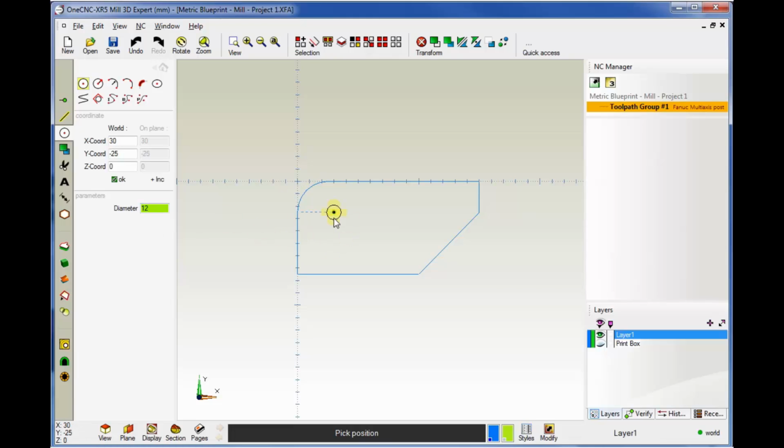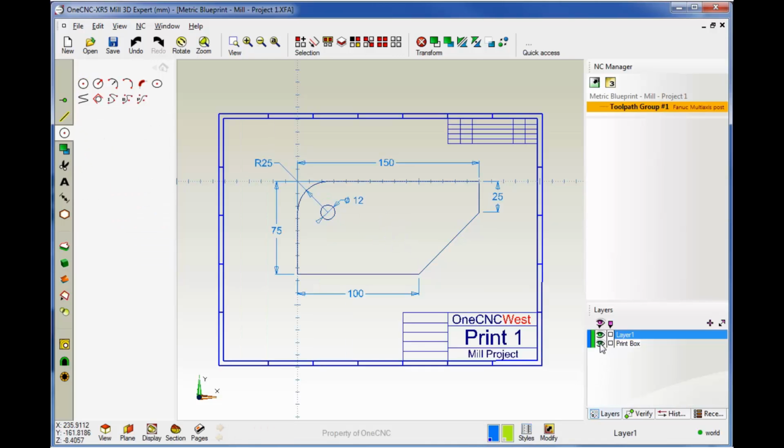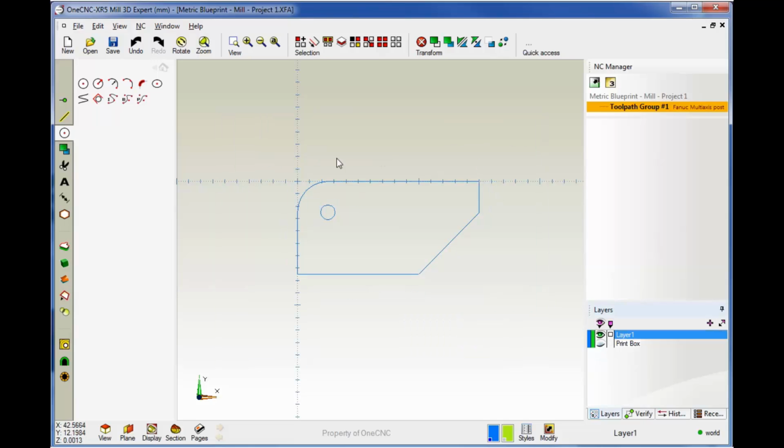What we'll do now is put that at the arc center of this. To do that, just take your cursor and wait till you see that little diamond symbol. You'll also see those little dashed lines. That also tells us that we're at the arc center. And then when you're done, you just left-hand mouse click. All right, that looks great. Let's bring our blueprint layer back on. And there's your very first part. Very, very simple